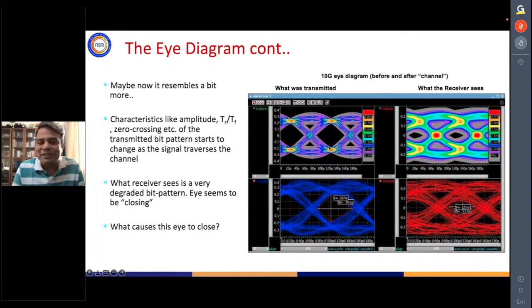This diagram just represents that if there is a zero, it is mapped to the negative voltage, if there is a one, it is mapped to the positive voltage, and the margin in between, where I have no bit present or no sample present, is my margin. That means my receiver can distinguish between a 0 and a 1. Why can it distinguish between a 0 and 1? Because the voltage levels are distinct over here. So if I have a comparator, I can make out what is a 0 and what is a 1 by comparing against a level crossing.